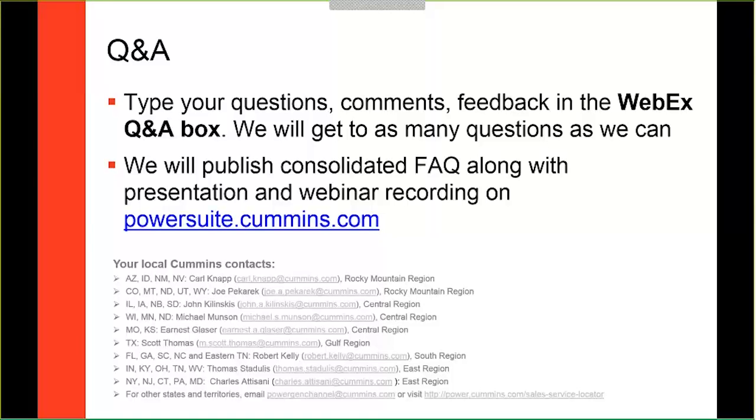So certainly we'd expect that most generator manufacturers are testing their ratings to ensure that the product can perform as expected in the field. Looking for things like a prototype test certificate or prototype test summary might be helpful for you to understand what has been tested by the generator set manufacturer and what they've done to make sure the product's going to work for you.